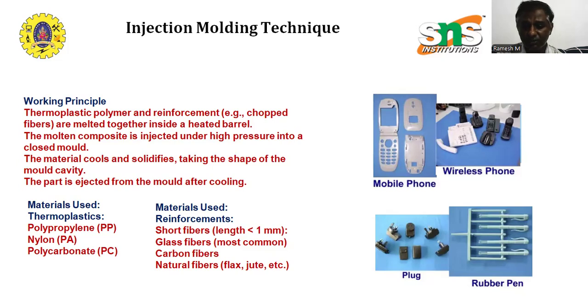Then the two mold plate here consists of two halves fastened to two platens of the molding machine's clamping unit. When the clamping unit is opened, the mold halves separate. A mold can contain one or multiple cavities to produce one or multiple parts in a single shot. The parting surface is the surface shared by the two mold halves.